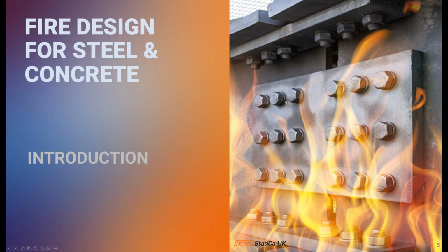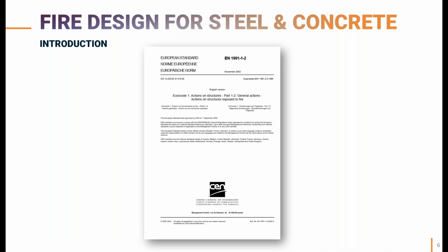Basically, for fire design, the generic procedures are described in detail in the context of the Eurocodes in a specific part. This is EN 1991-1-2, which basically defines actions on structures exposed to fire.